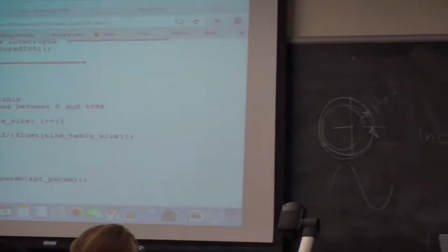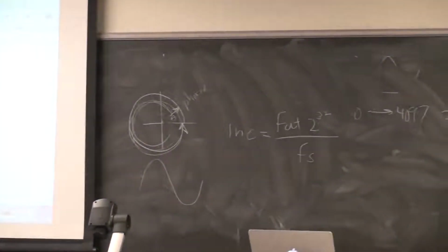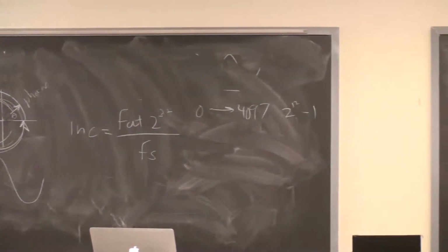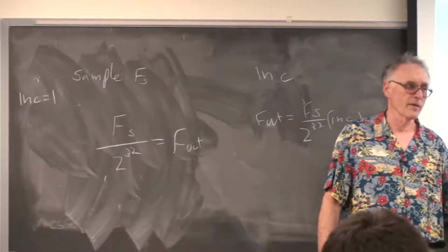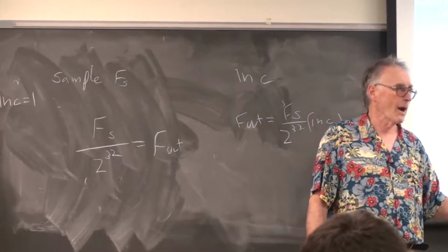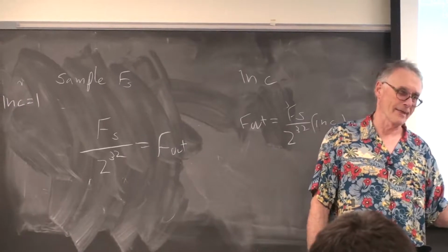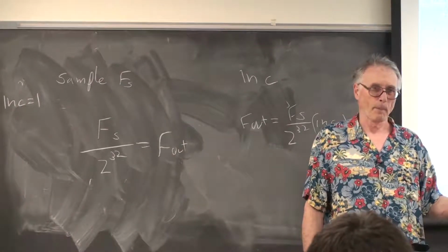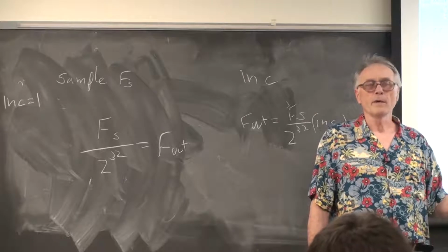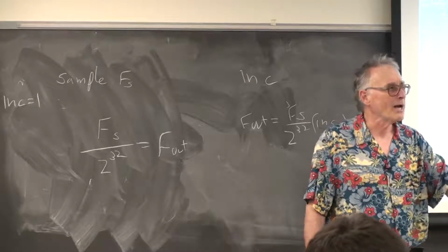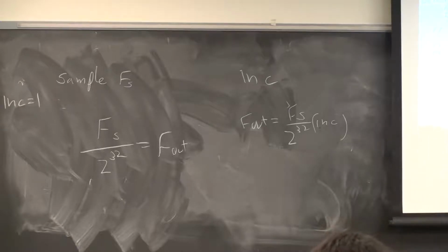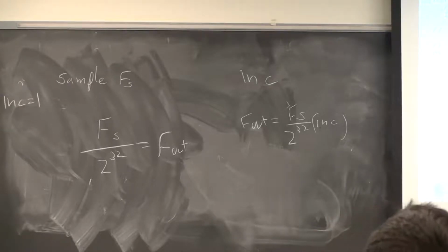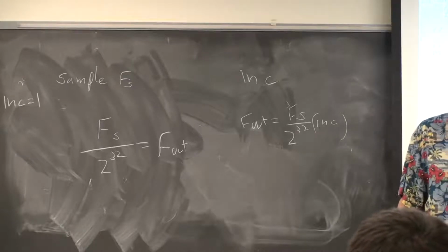However, this goes up plus 2047, minus 2047. The DAC requires a strictly positive number between 0 and 4096. So why didn't I just make the table 0 to 4096? The reason is that when you are modulating this function, when you're actually making an amplitude dependency, you want 0 amplitude to map to 0 output.